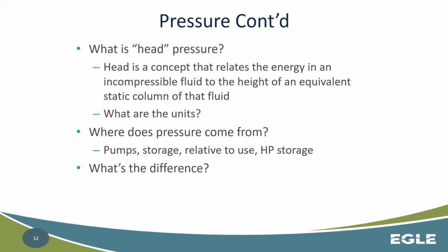And for hydropneumatic storage, air can be compressed in a tank which has a membrane barrier separating the water from the air. So as we set air to a certain pressure, or we're pumping air into this membrane, we can then pump water to push up against that membrane and reduce the volume of air on the other side of that membrane, and therefore increase the pressure of water.